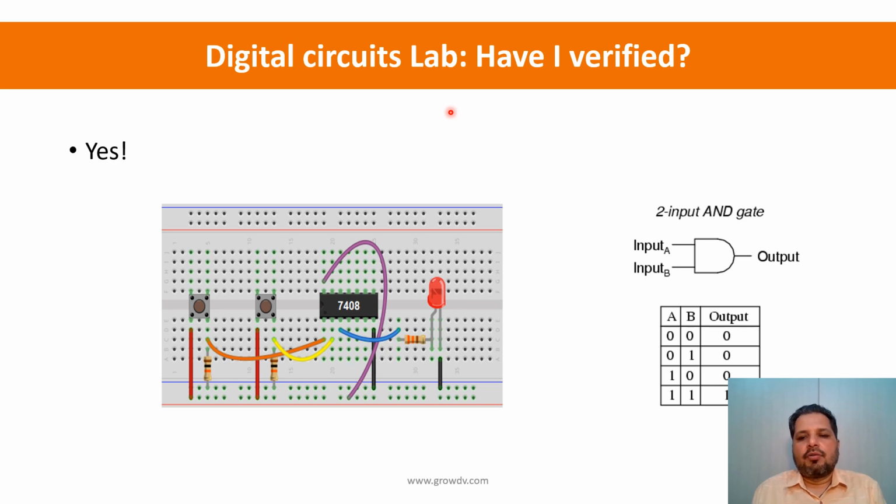The way you would have performed your lab is that you would plug this particular IC into a breadboard, power it up, and take the truth table that's present on the right side. You'll pick each gate, and that gate will have two inputs and an output mapped to some pins, and you will use wires to go through all four combinations, 0 0, 0 1, 1 0, 1 1, and check that the corresponding output matches the expectation by looking at some LED or on an oscilloscope.